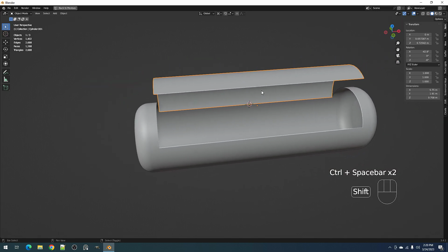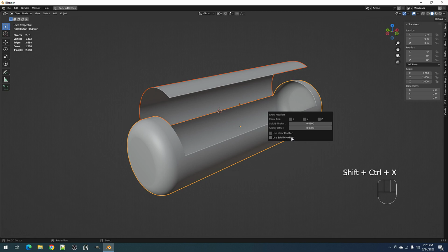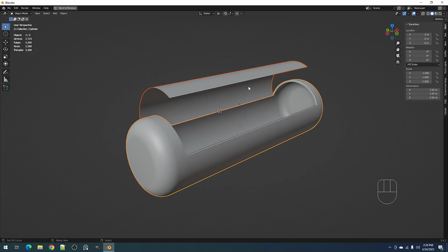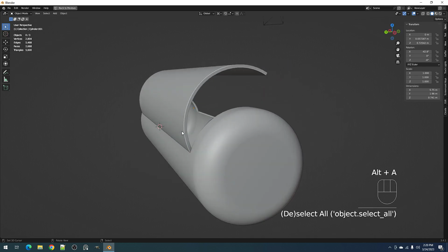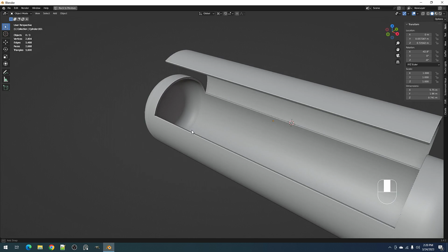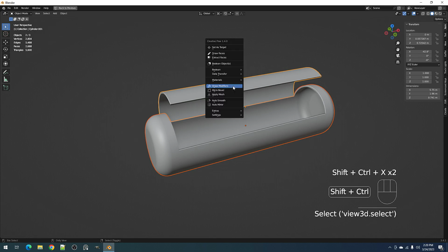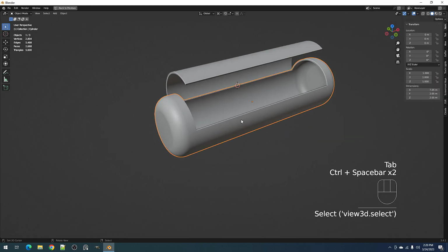And let's give this geometry thickness. Add modifiers. Use solidify. Oh, it only works on the active object. So 0.05. And same here. Use solidify modifier, 0.05 as well. And then we're going to apply the solidify modifier so it becomes a real mesh. And we establish the mirror on the main body of the cylinder.